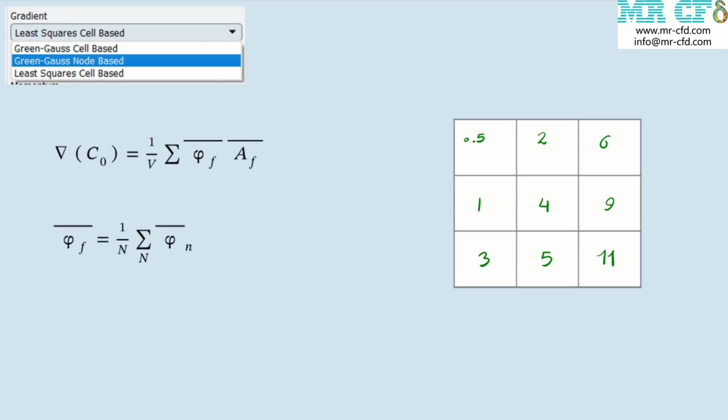In two-dimensional cases, each face usually has 2 nodes, whereas in 3-dimensional simulations, a face can have 3, 4, or even more nodes. The value at each face is calculated by averaging the node values of the adjacent face. The value at each node is determined by the weighted average of the surrounding cells, where d is the distance of the center of the cell to the node.